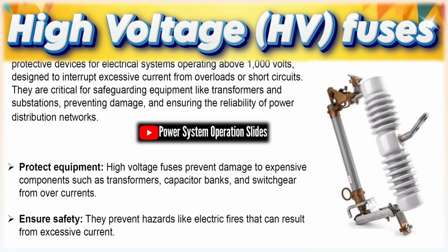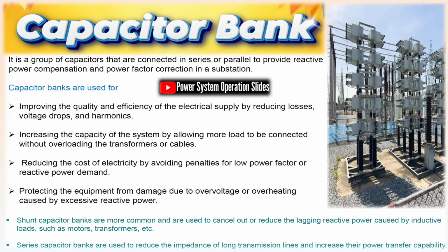Double bus single breaker. Two buses feed circuits via a single breaker and bus coupler. Provides flexibility for maintenance and switching between buses. Protection is complex and relies on couplers for continuity.